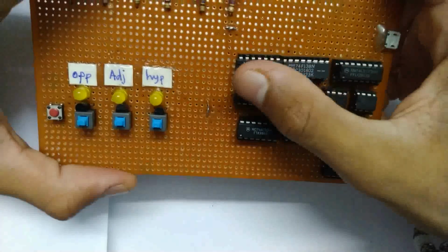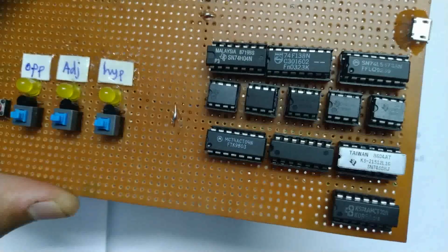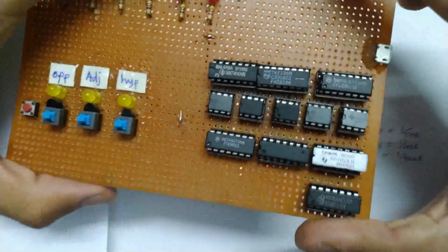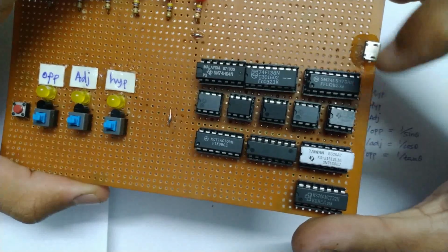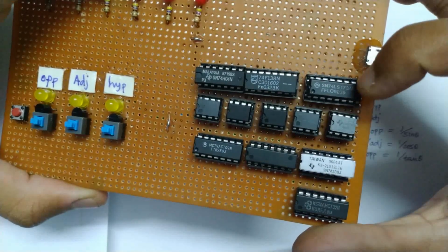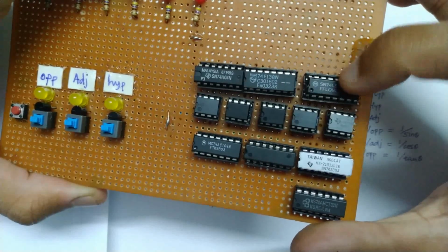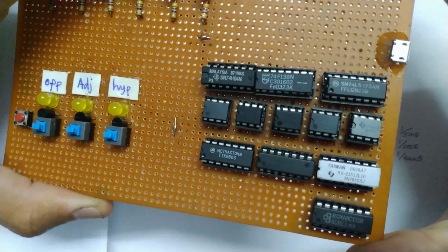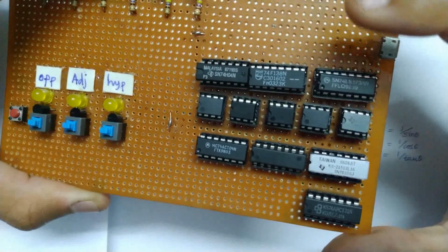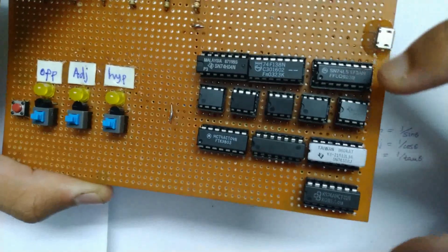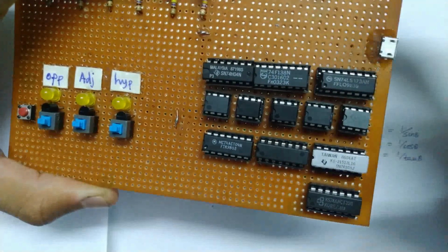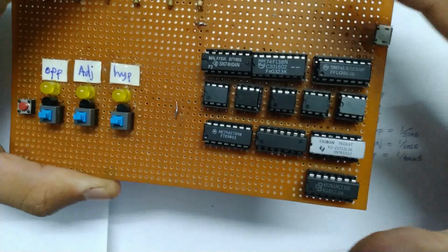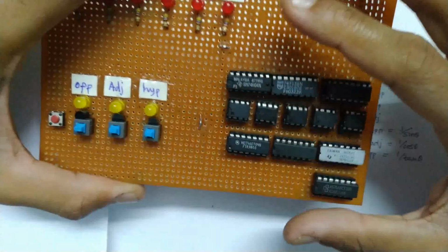And these ICs over here are just 555 timers. Yes, all of them are 555 timers. 1 2 3 4 5, 5 555 timers. And then there is 74173 quad D flip-flops. This is just an IC which contains 4 D flip-flops. It can store 4 bits of memory. It has a few essential pins like output enable. Then this is a tri-state IC, which means it can give high impedance outputs, but that is not necessary in this particular problem statement.